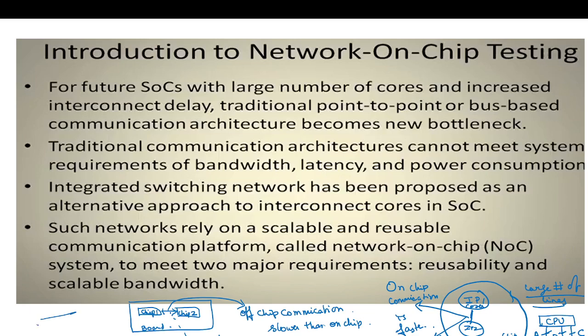So we have multiple lines running at high frequency, say gigahertz of operation. So there is a chance of crosstalk and interference. This is called point to point communication. If we have this point to point communication, we are going to have huge interconnects. And these huge interconnects, or the large number of lines running, are going to lead to crosstalk and interference.